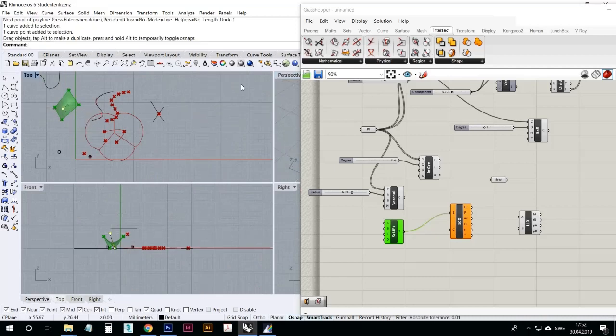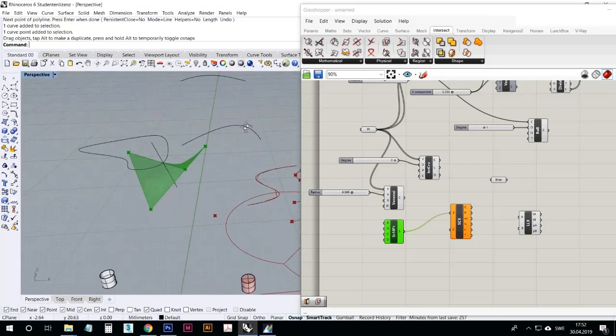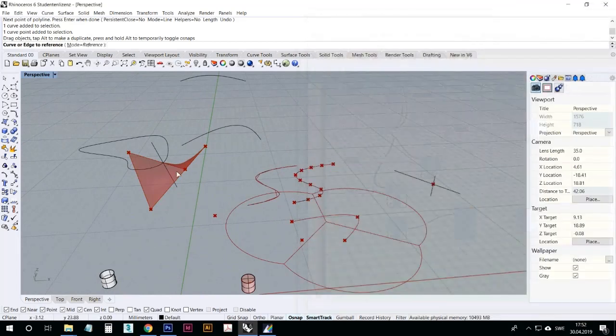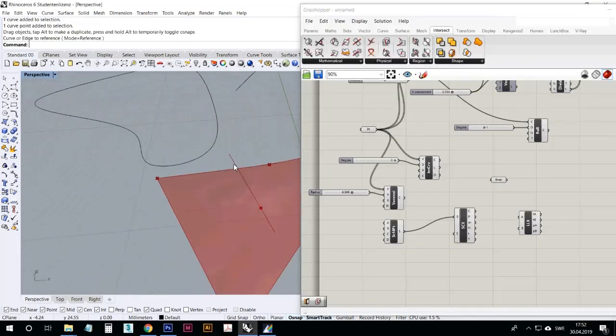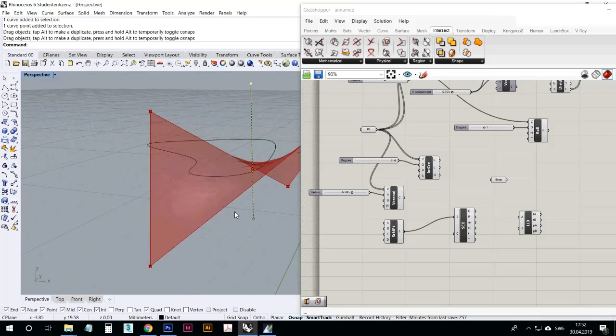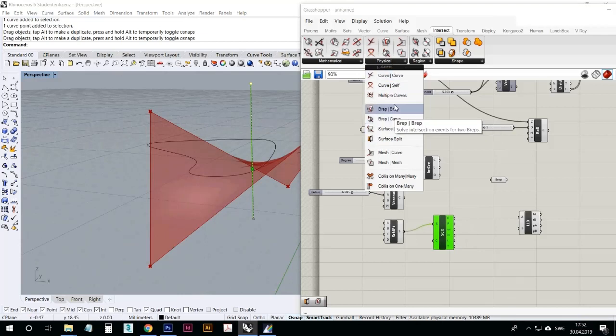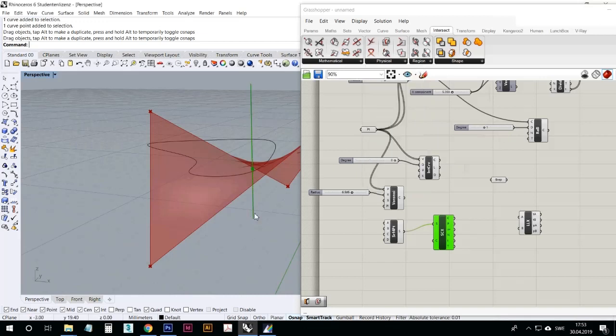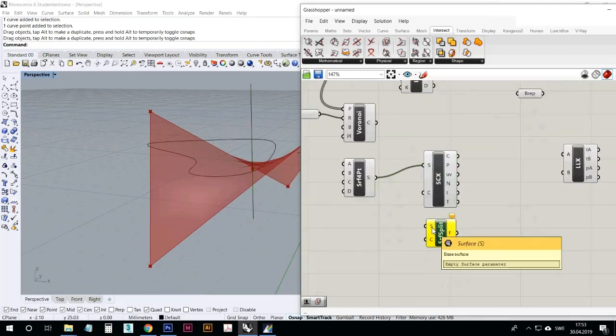There. Now I know that it's going through, right? But we can still try to get that curve. And the fine part here is that every time I move this curve, a new intersection point through the surface is going to be generated. So this is more or less how the intersection physical section here works. Then you can, of course, also split the whole surface, which you do with this component, which looks much easier. So one surface goes in, and then you have a curve that is projected on the surface, and it will split it in 2 frames, very much like this.